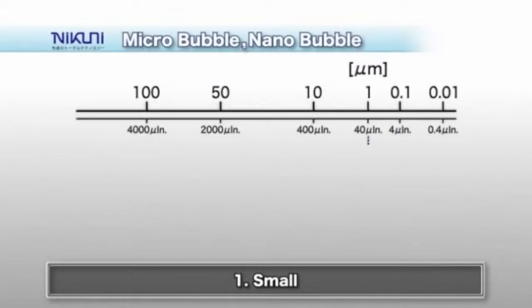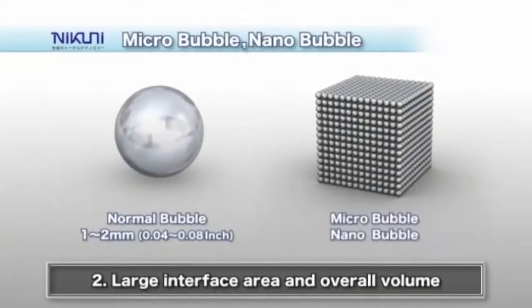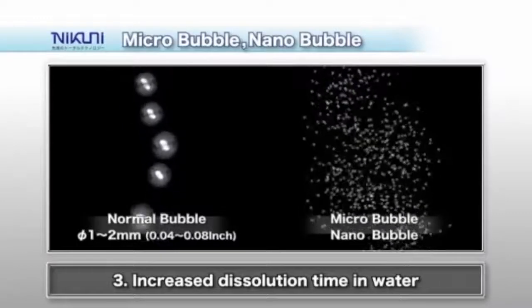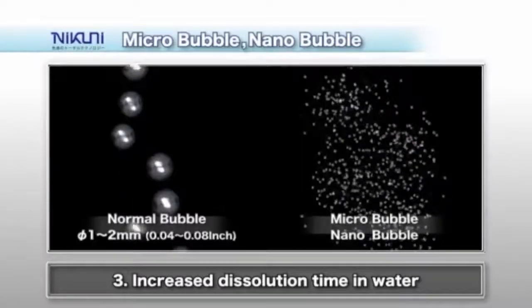A clear advantage of Nikuni's micro-nano bubble technology is a very small bubble diameter. Air bubbles produced by our system have an average diameter of 5 microns. Compared to bubbles that are produced by conventional systems as big as several millimeters in diameter, there is an enormous number of micro-nano bubbles in each cubic millimeter. This creates a greater interface area and overall volume of bubbles. Compared to other methods, the micro-nano bubbles remain dissolved in water for a long period. Thus, they readily adhere to suspended matter, providing the best flotation separation performance.